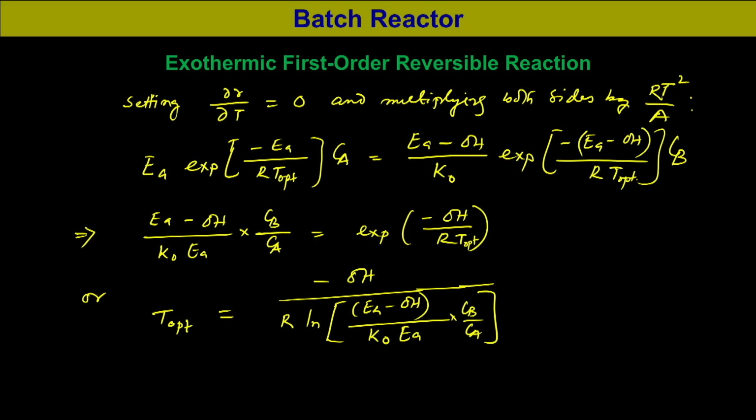So, the optimum temperature becomes infinite when the quantity inside the logarithm in the denominator is equal to 1. So, as the reaction progresses, the conversion changes, the term over here in the denominator under ln terms becomes 1, then it indicates the optimum temperature is infinite.